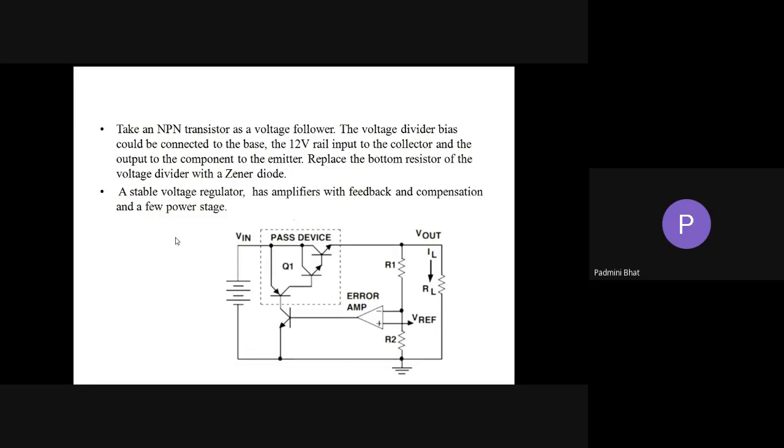Now, if you see this diagram, this is the error amplifier. Now what it does, at every interval, it takes a sample of the input through R1 and gives it here. This is a comparator now. You have studied about comparators, right? This is the reference voltage. At present my reference voltage is 5 volt.